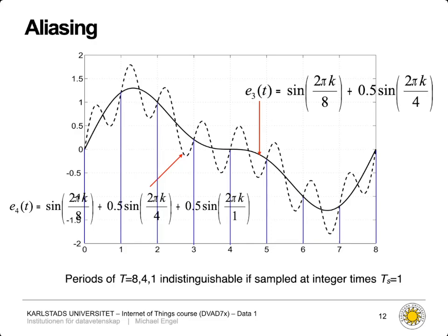So this is one of the general problems when you are trying to discretize time, that you need to adapt your sample frequency to the properties of your signal, so to the highest frequency of the signal that you're going to measure. So you need to know something about your signal. And in very many circumstances, you know it. So let's assume for audio signals, if you want to, for example, record human voices, you might be happy with a frequency range of human voices between 0 hertz and 20 kilohertz.